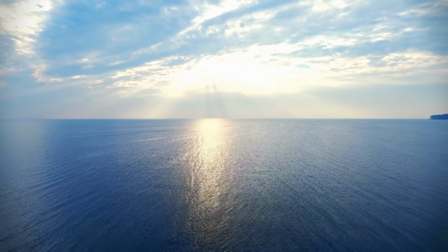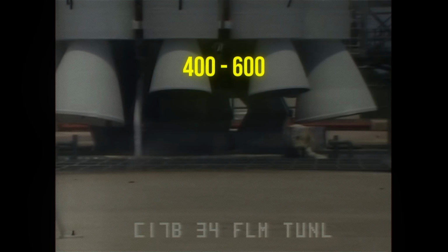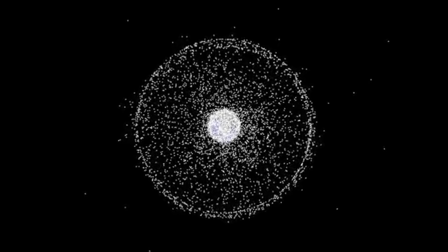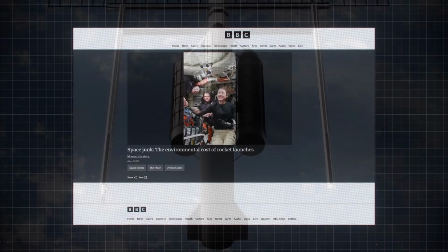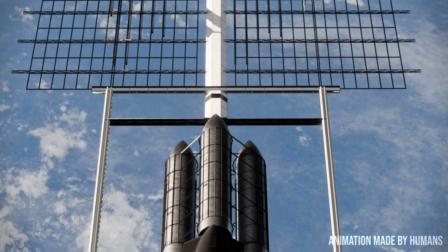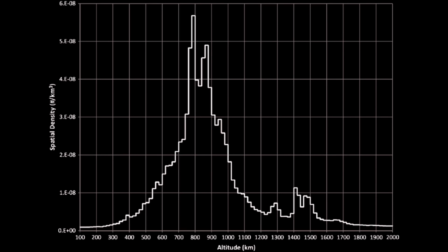drag. Sure, that extra 400 to 600 kilometers will amount to an increase in cost, and sure, space debris is generally exaggerated in the headlines, but because we are actually building so large, we're basically volunteering to be the poster child for the next space traffic outrage cycle, and so it's my opinion that 1,200 kilometers is a good compromise between all these factors, giving us a cleaner story for licensing and insurance.